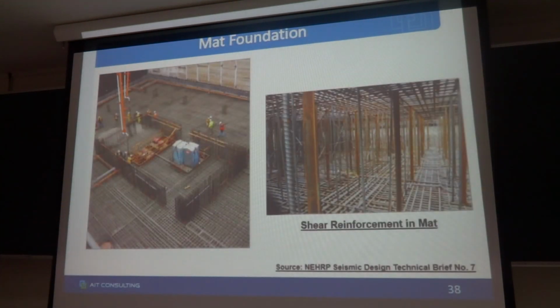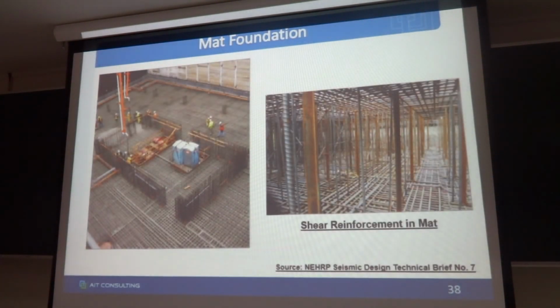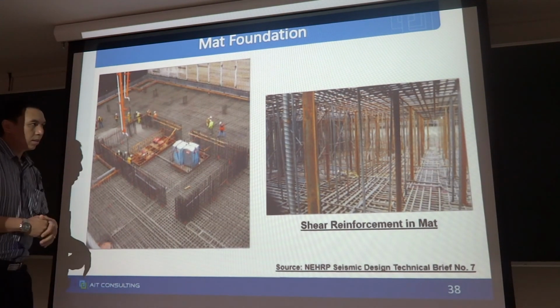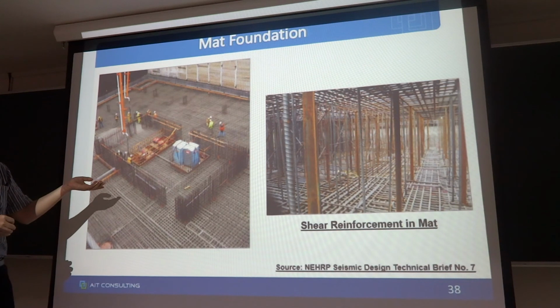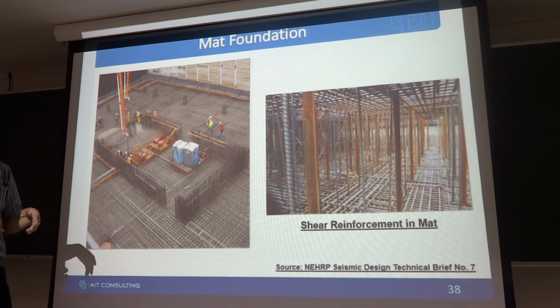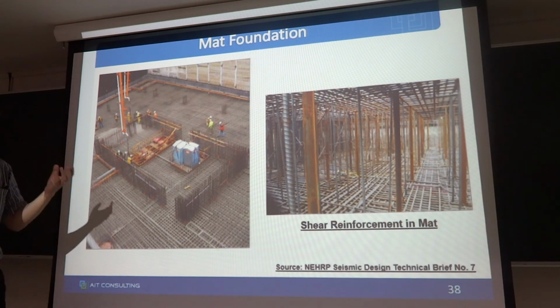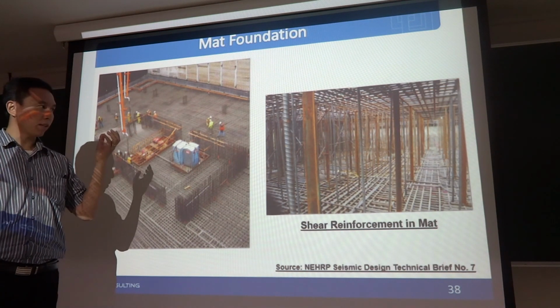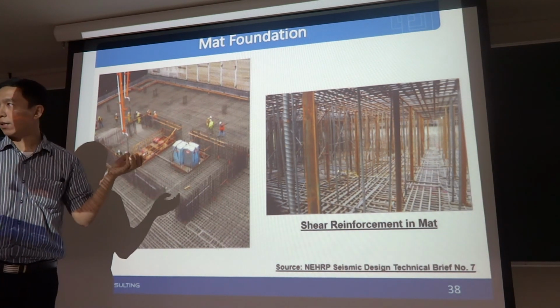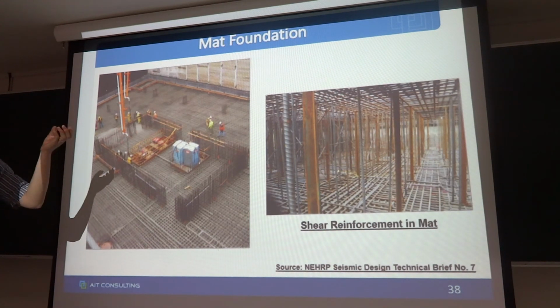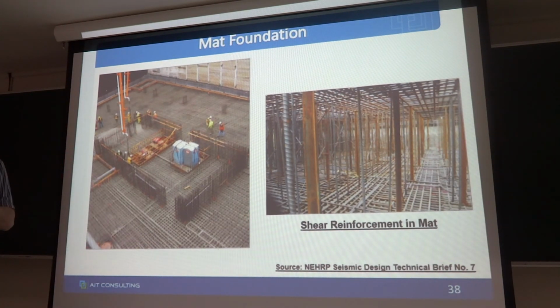diaphragm. Okay, mat foundation. For mat foundation, we have to check for flexure and shear. Normally we check the shear capacity of the mat first to determine the thickness. After we design for shear, we continue with the flexure design.